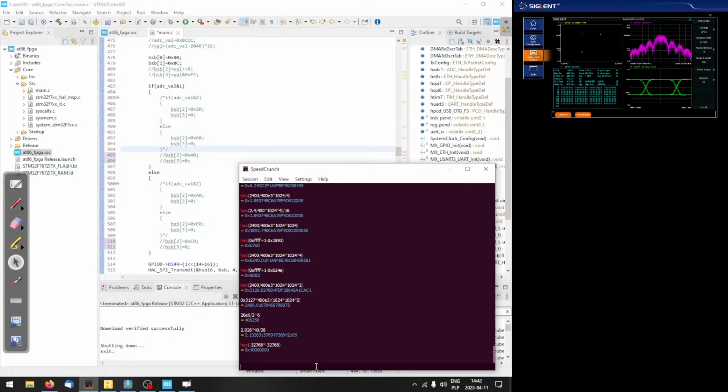You can just set the plus and minus 1 to the maximum and the minimum value for that range. Because if we did that, you would see some clipping going on, and that's of course not desirable, because that causes some spectral splatter and unwanted emissions. So that's not good.